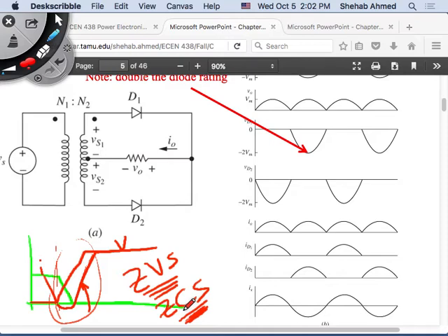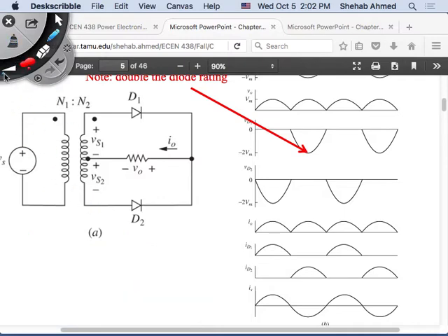And we will not cover those. I mean, that's a family of converters, a special case of converters, and their objective is to reduce losses further and further. Right? We will cover the main types of converter topologies. And you can do zero voltage switching, zero current switching on all types of converters, not only DC to DC converters. You can do it on DC to DC converters, DC to AC converters, AC to DC converters. So on all families of converters that we will study, we study the general case where we don't study the zero voltage switching case. In all our cases we will consider the voltage falling, current rising, and we always have power losses.